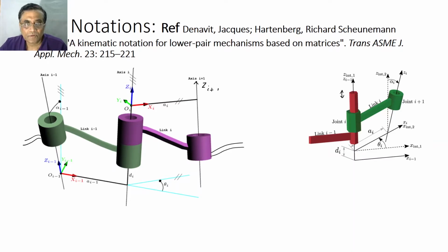So far so good. Wherever you have a rotation axis, or motion axis, you assign Z. Just like link i, Z i should be here at the left. This is the convention of our notation. So Z i, and where will X be? You figure out the distance between the two axes of rotation, and that characterizes the link length.